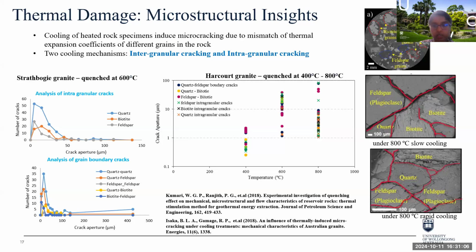The results show that propagation of cracks through grain boundaries significantly increases with the increase in preheating temperatures. Increasing temperature further creates thermal stresses in the rock mass due to its natural anisotropic nature, because rock mass consists of different minerals and they have different thermal expansion coefficients and thermoelastic moduli. Once thermal stress exceeds the internal strength of the rock matrix, fractures are initiated through pre-existing grain boundaries along large grains.